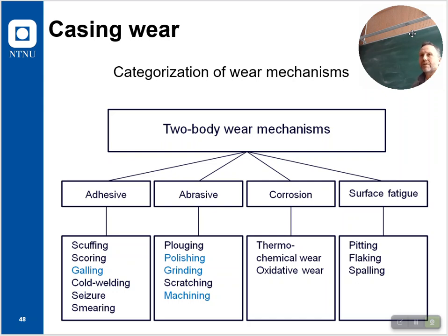and that's adhesive. It looks like you have taken a piece off. If you're going skiing and you put the wrong stuff under your skis, the snow sticks. That's what happens when you use the wrong thread compound and you try to make up two pieces of stainless steel. You tear off a portion of one of them, and it sticks to the other one like snow under your skis.